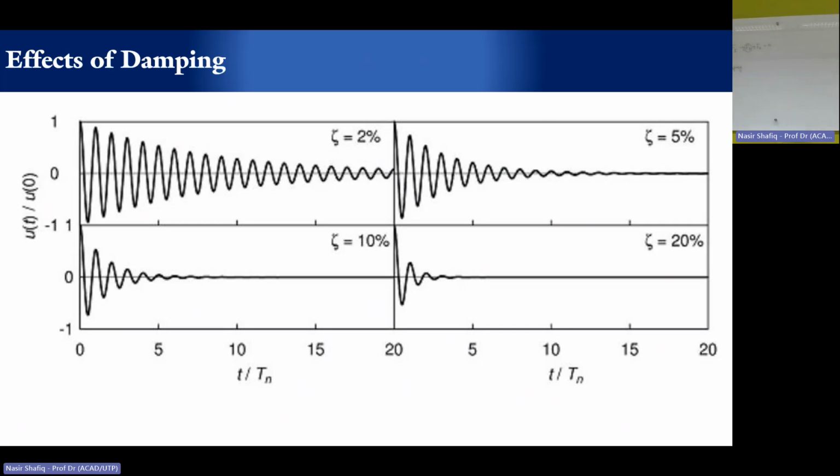Normally most of the building structures or even offshore structures are designed for a damping ratio between 5% to 10%, because we would like to maintain the stability depending on the characteristics of material and geometrical sizing. This is what most engineering design for building structures, bridges, or offshore structures has to do.